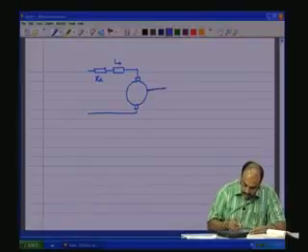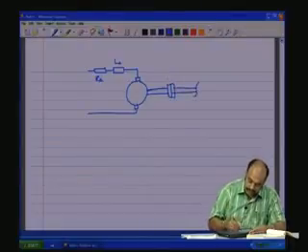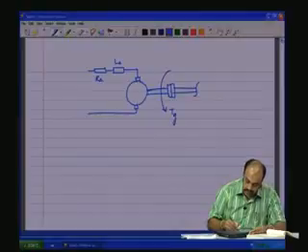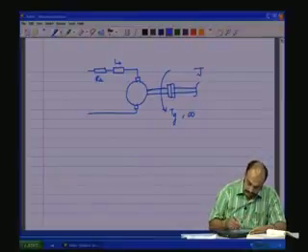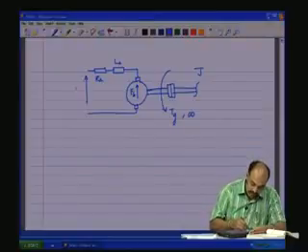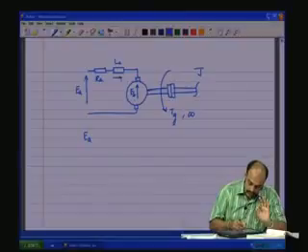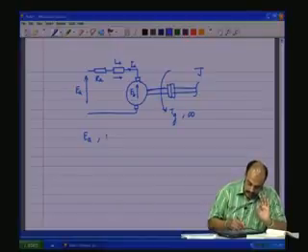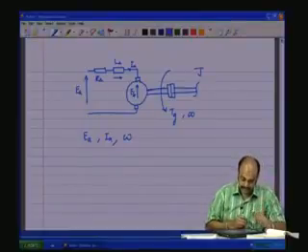And we have the mechanical shaft. So, here we have the TG and omega, there is reflected inertia, we have the back EMF EB and the input EA. Now, to get the state space model, I have to express it only in terms of EA. There is an IA which is flowing in, and another state variable omega, just like in the case of a DC generator.